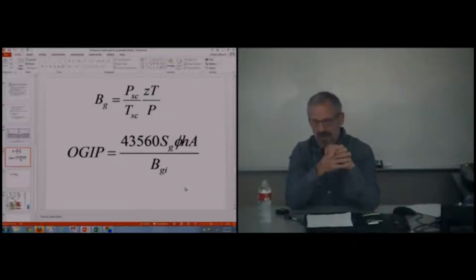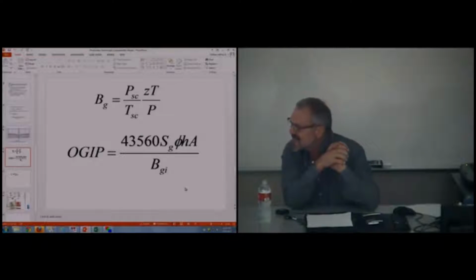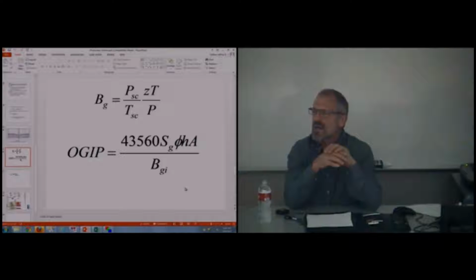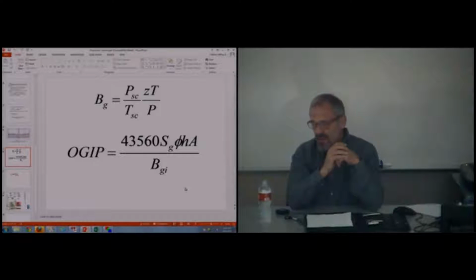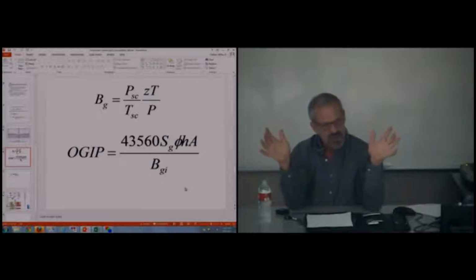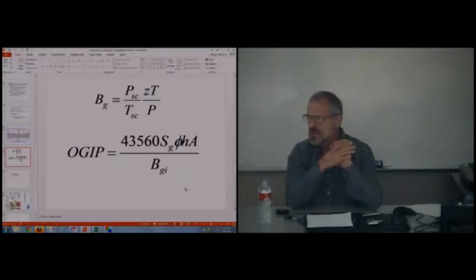I'm going to talk about this right away. Which means that it is not irreducible, and that when you put this well on production, it'll produce water and gas. And in Oklahoma right now, there's kind of a boom in what they call dewatering projects, where they actually try to drill into reservoirs that used to be avoided because they produce so much water, and they found out that they can produce a lot of this water off, and they can actually reduce the water-gas ratio and get a lot of gas out of these reservoirs. So that's kind of an unconventional drilling or production technique that's going on in Oklahoma.